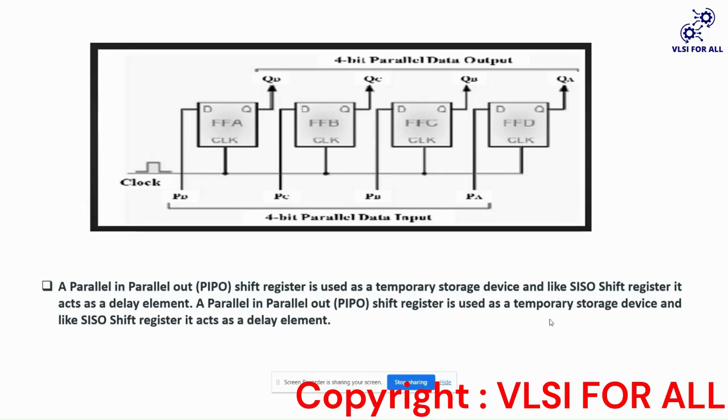Verilog code based on parallel input, parallel output shift register. Before going into the Verilog code, let us discuss what a parallel input, parallel output shift register is. We may know that shift registers are mainly of four types: serial input serial output, serial input parallel output, parallel input serial output, and parallel input parallel output. Today we will discuss the parallel input, parallel output shift register.